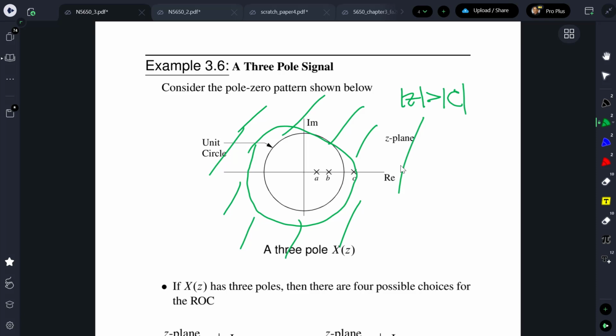I thought, with those properties we were reviewing earlier, if they were inside the circle, they were left-sided, but because they're on the right of 0, they're all right-sided because they're positive integers? Well, it's not because A and B and C are positive or negative. It just has to do with the region of convergence being the exterior of the largest pole radius. And of course, the ROC can't contain any poles, so it's a valid ROC, but all 3 of those terms are right-sided.